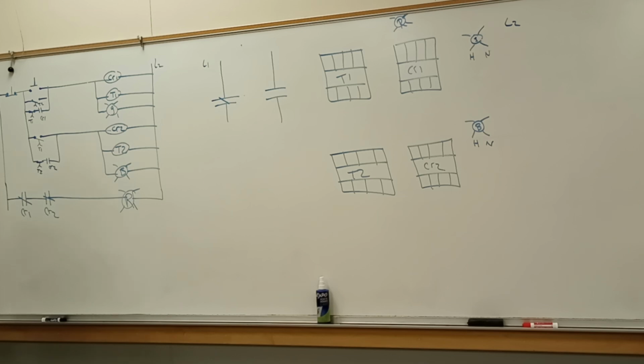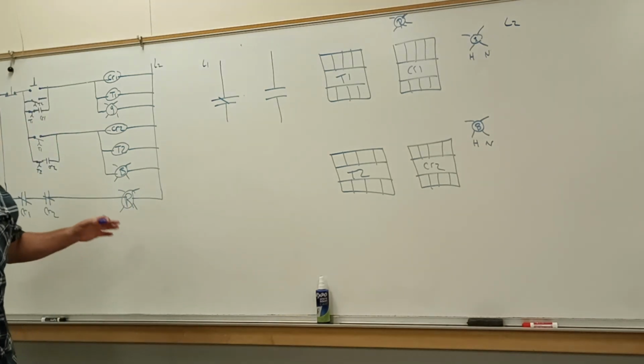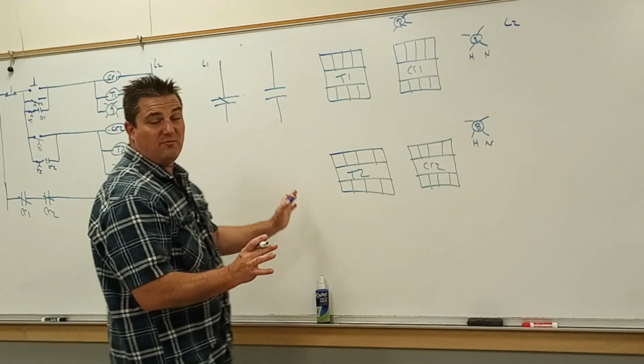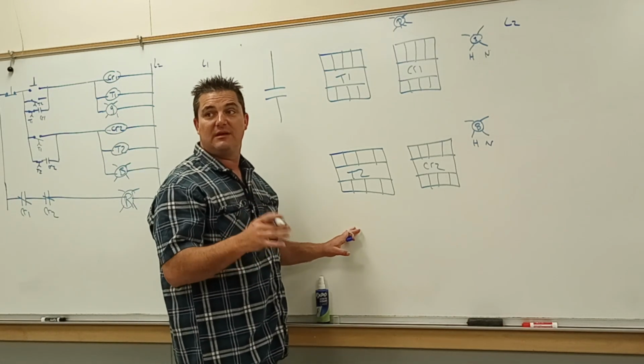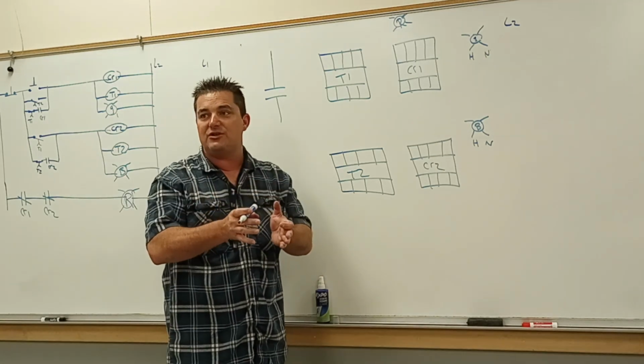So I'm going to start at the beginning. I'm going to do the red light last because that's the easiest one, not going to be nearly as much to do. As you're starting out, an easy way to help you take a ladder logic and develop your wiring, and while we're using these bases, because remember, the bases change configurations.